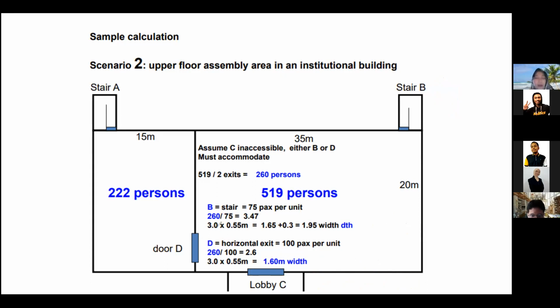So the way we calculate is same like the upper part. This is actually based on schedule. This is also when you get the total here, this is also based on schedule. If 3.47 is not exceeding 3.5, you have to take 3.00 times 0.55. This is as per the minimum width per swing from the schedule, from the bylaw. This is bylaw. Don't ask me why 0.55.